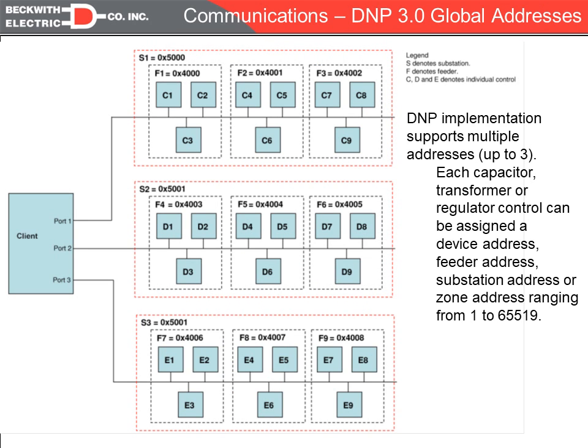Finally, we have a global scheme that we've added to the 2001D, and this is for serial DNP communications. Typically, DNP does support a global address, where if you receive a direct operate with no acknowledgement, either analog or digital output, you would act on that control. The problem is other devices and other vendors also would support that global. So we were requested to come up with our own subglobals.